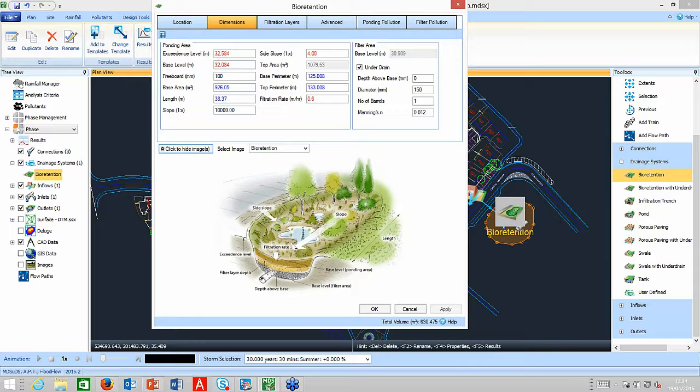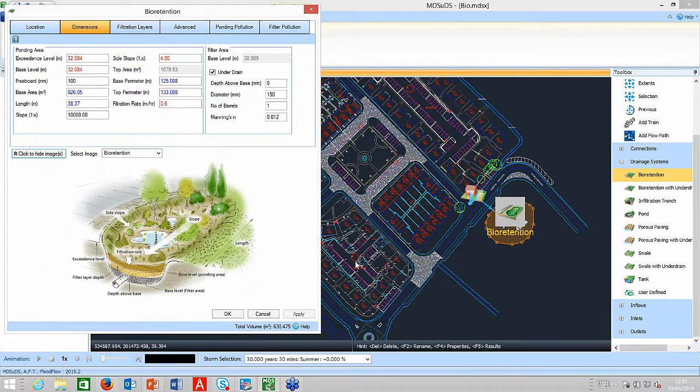The slope, this is the slope on the surface. I put it in really flat, 10,000, could put in 0 for absolutely nothing at all. And because we're just outside of the infrastructure, the highway, etc., there's a bit of public open space or open land here. So I'm going to let my hair down just because I can, and I'm going to put in 1 in 4 side slopes to have the runoff entering across and then into the structure.